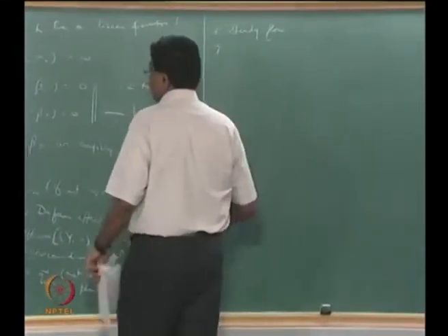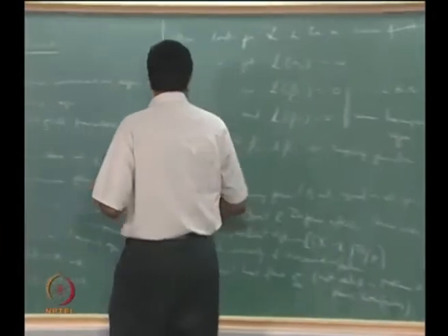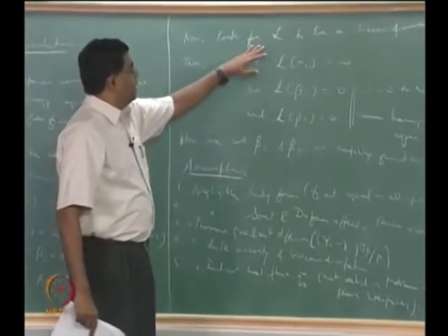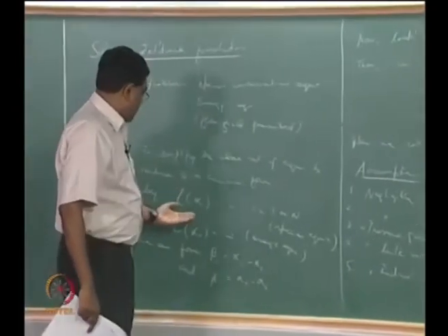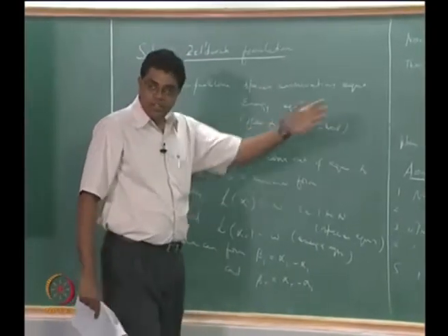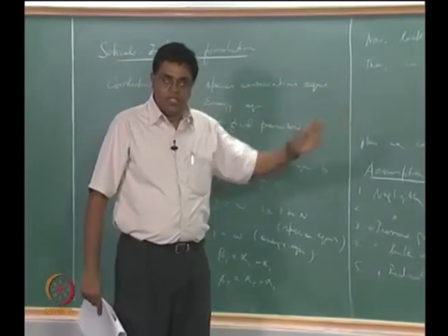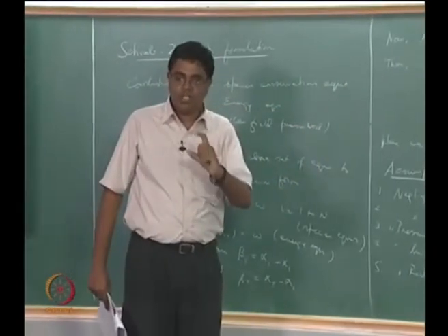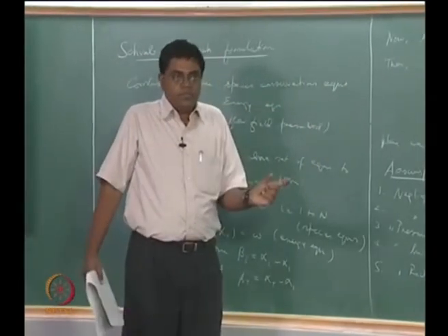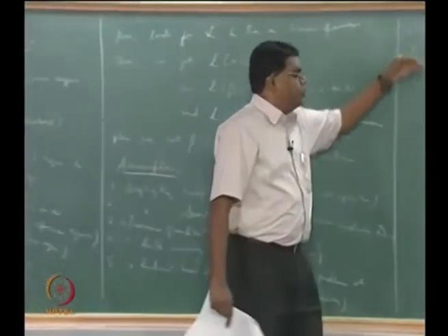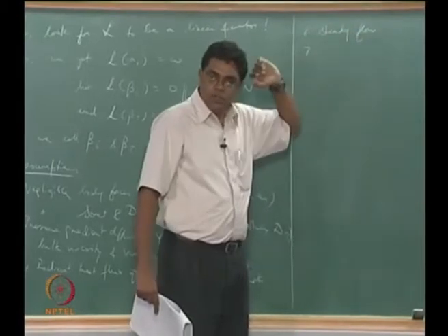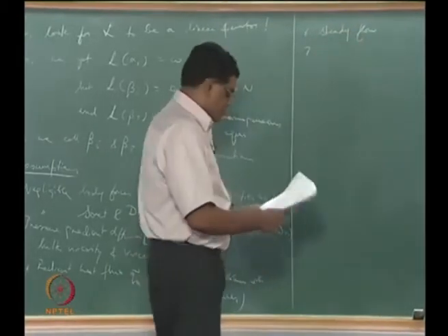And keep in mind, what are we looking for? We are looking for a script L operator that should be linear, and typically the time derivative, dou by dou t, is a linear term, it's not showing up any nonlinearity, so you shouldn't have a problem with unsteady flows at all, so you should be able to relax this assumption.